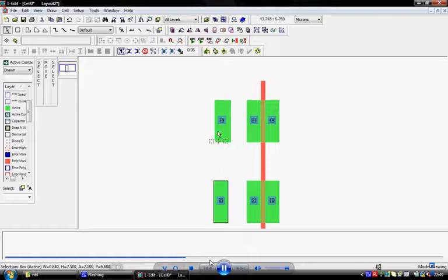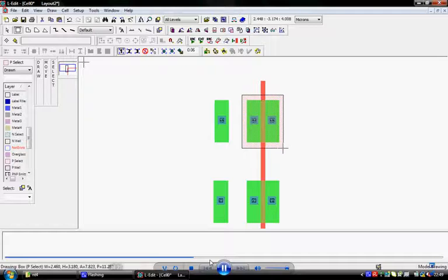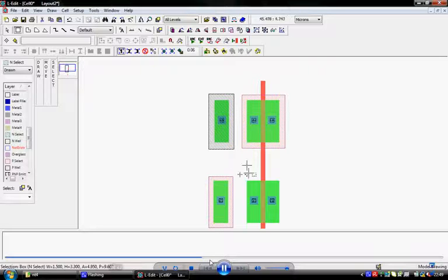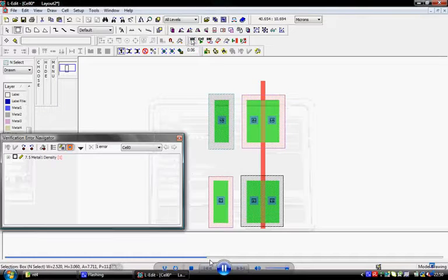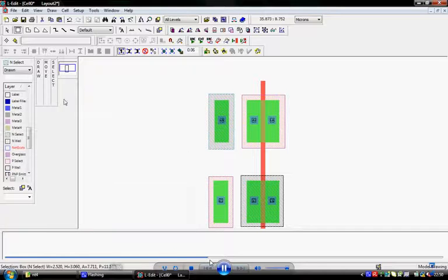Now try to minimize the layer, make it even, uniform. Now place the select layers. First select P select layer, drawing boxes, then draw the P select layer for PMOS, and P select layer for ground. Next N select layer for VDD. After placing for NMOS, N select layer, DRC. So metal 1 density error can be neglected because metal 1 has been used there.